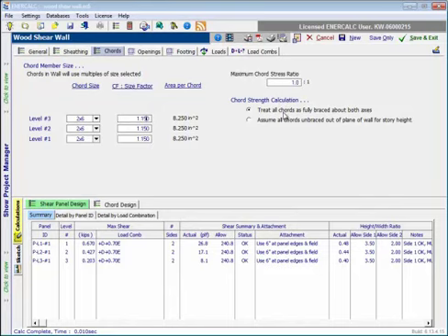This is a way that you can do that, but the intention for normal use, for new construction, for all normal loads and load combinations according to today's building codes and design standards, we would expect that 99% of the time this will be set to a value of 1.0. So we're looking at just meeting allowable chord stress ratios.